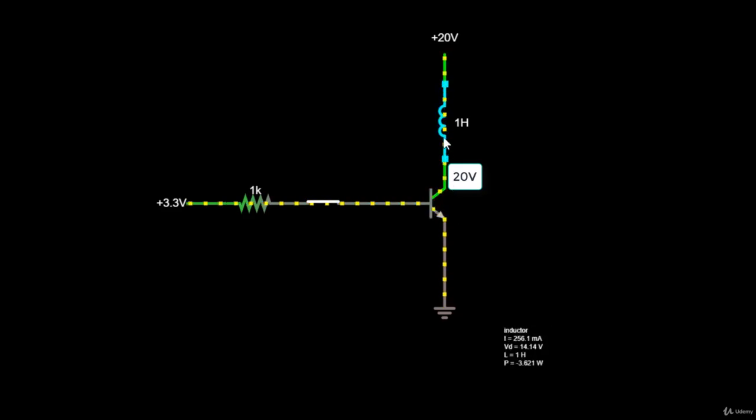Now let's suppose you want to turn it off. You open the switch and notice the back EMF in action. The voltage on the collector suddenly rose to negative 102 kilovolts. There's no transistor that could handle this voltage on its collector, so once you turn the motor off, you can as well throw out the transistor because you have blown it up. In real life, the voltage here again wouldn't oscillate like here. There would be a huge negative spike that would instantly blow up the transistor.